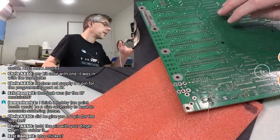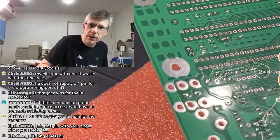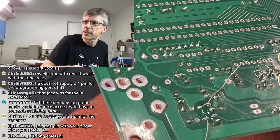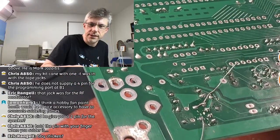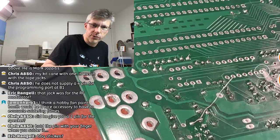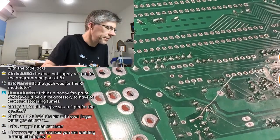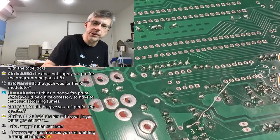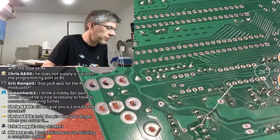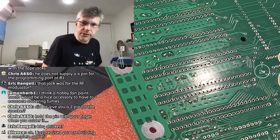All right, let me zoom in. It's hard to get it to show up in the camera. All right, so you can see it looks a little messy just because of all the flux all over the board because I haven't washed it off. But there's the 4-pin connector, and I've taken that lead from that capacitor at the C14, and I've just soldered that to that 12-volt line there. And then we're just going to go ahead and clip off those extra wires.